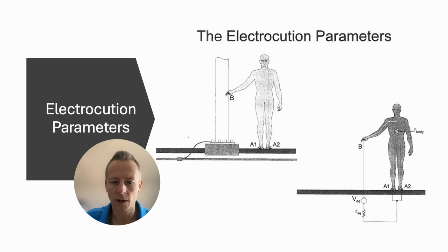Here's just another one of what IEEE Standard 80 depicts as the electrocution circuit. You're touching something grounded. You're standing on dirt that is not touching the grid. So this dirt, you're right above the grid, so maybe it hasn't fallen off from the GPR too much, and it's not too different in voltage, but there is some voltage difference, and that's the shock circuit.